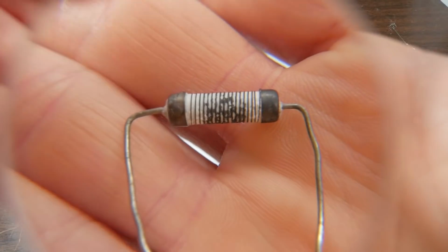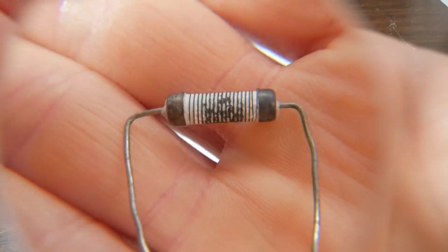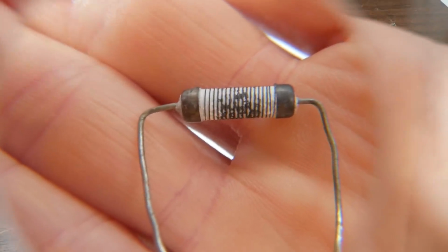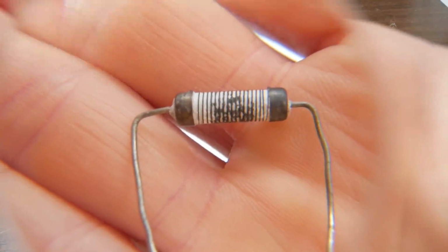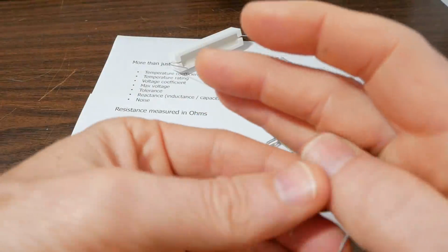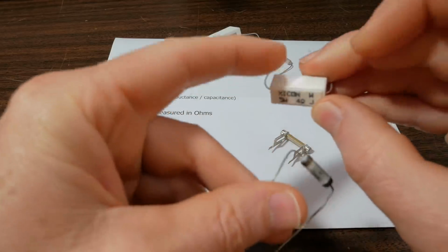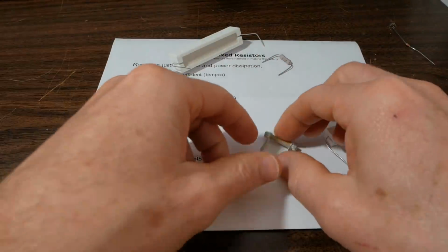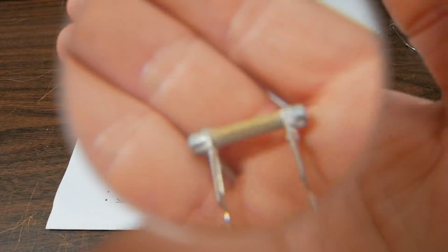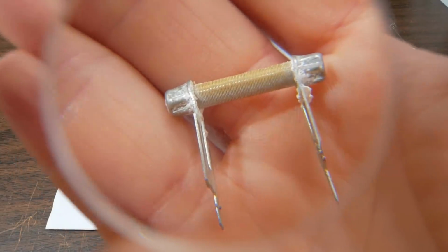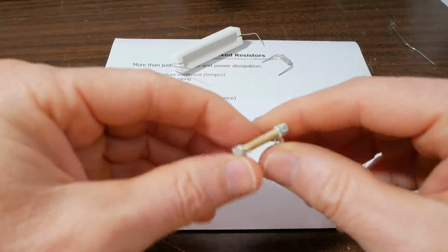I didn't do a drawing of this one. It's pretty large. You can see it has the metal end caps with a spiral of thin wire, and that could be an assortment of different materials, probably nichrome. This is in fact one of these, which I broke the outer casing off. Here's another one that's a 220 ohm, and see if we can get that in focus. Has really fine wire, so you can probably guess an issue with these.